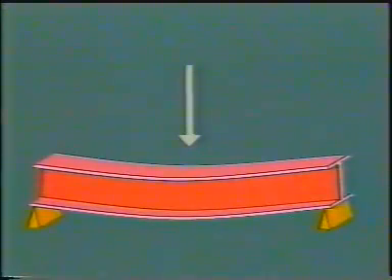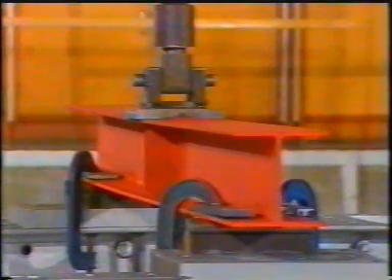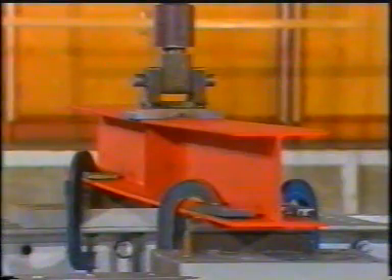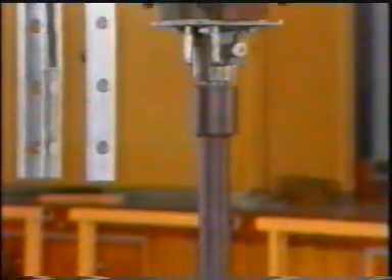The next three tests all concern simply supported beams of varying slenderness. A central vertical load, causing bending, is increased to failure in each case. The first beam is just over a metre in length and can be described as being short and stocky. The load is applied to the beam by a screwjack device via a vertical rod.